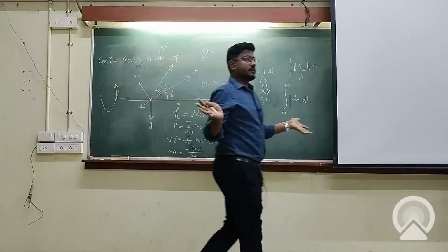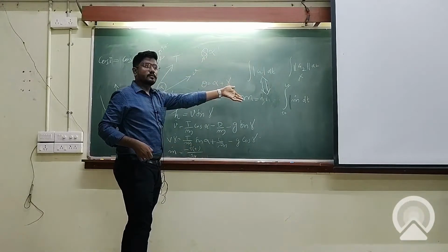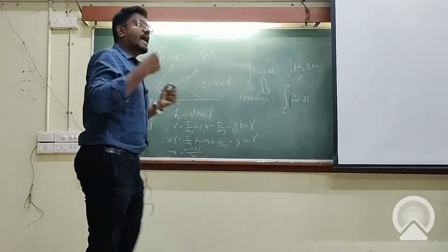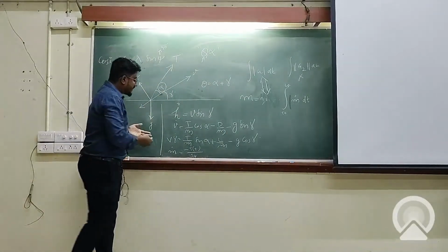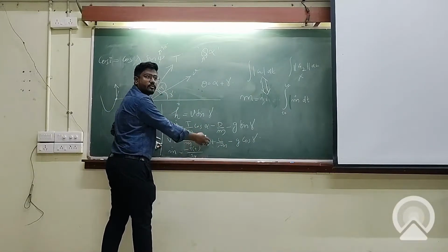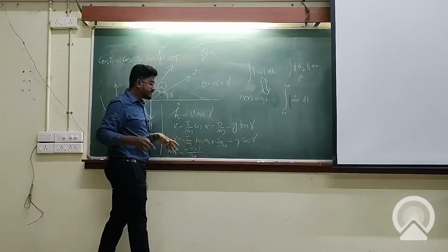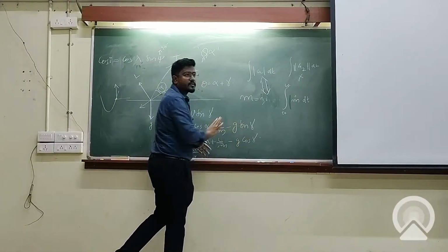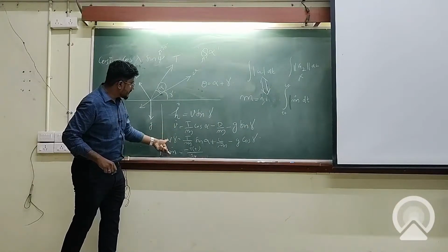Those are all going to be easy as long as you don't have an alpha. Right? Q alpha will be well within the limit. That is what we are doing. But what is the consequence? When alpha goes to 0, what happens to speed? You can see gamma dot: when alpha goes to 0, P by M sin alpha goes to 0. The lift is also not there, CL is 0. Your gamma dot can be written as minus G by V cos gamma, and your V dot as minus G sin gamma.